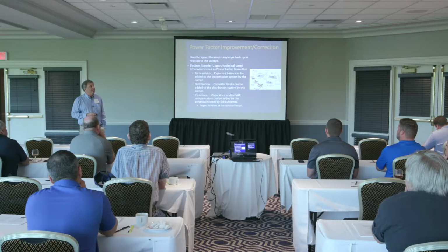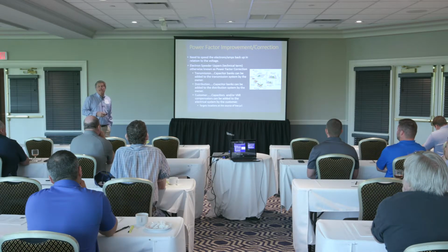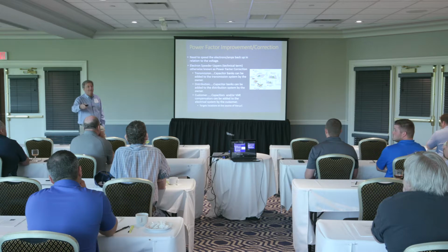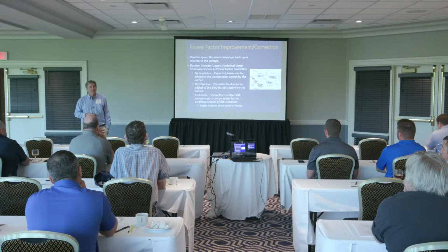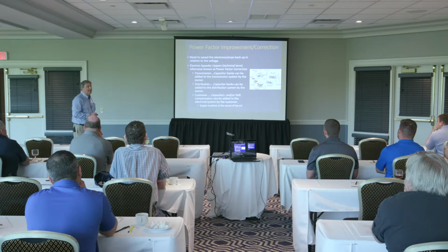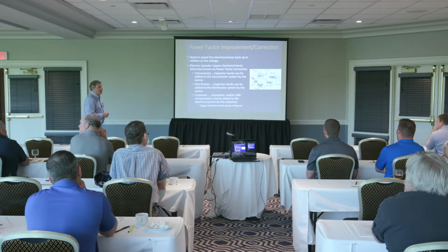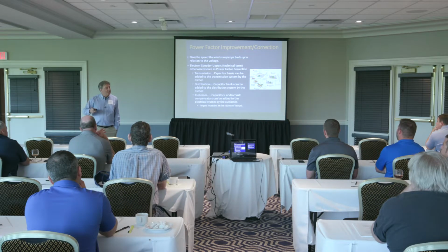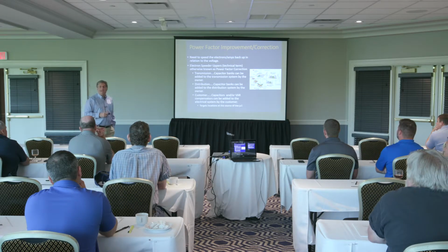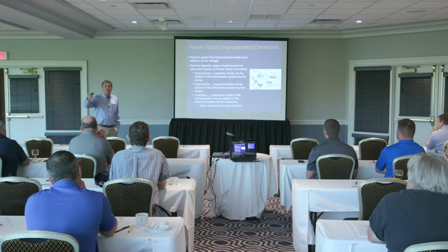And as I said, the explanation now is instead of paying the utility to provide that reactive power, we're providing it ourselves from our capacitor bank. So we no longer have to pay them to provide that reactive power. That's how you explain it, make your business case. And if we do the calculation, typically you as the customer can buy the power factor correction capacitors and install them cheaper than you can buy the reactive power from the utility.